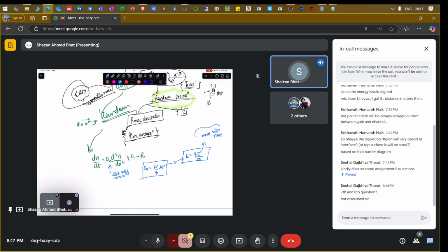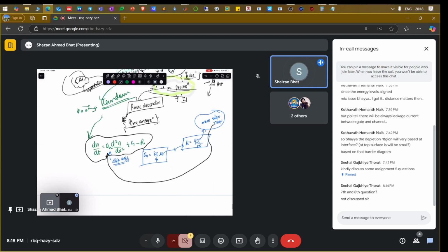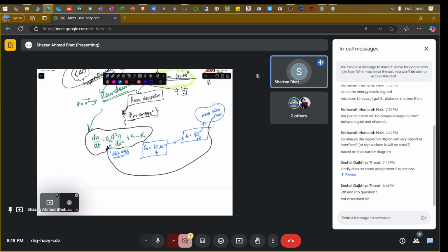So you see these quantities are all involved, and because of the inherent statistical nature, they can go in reverse fashion, and they affect this particular diffusion process also. And whenever we take the average quantities, then we have all of the things as average: diffusion coefficients, the mobilities, everything. And that's basically the source of the noise. Whenever you have some random process happening, you have a hell of a lot of sources of noise in the system.